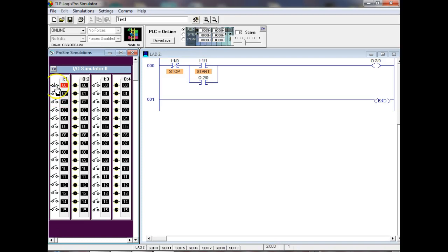Now notice what's happening. This is a normally closed push button, but it says it's true when it's open. But I'm using normally closed, so it's what? False. So I'm coming here all day long and pressing this, and nothing happens. If I change this to a normally open push button, now I come over and press this button, and it says it's true because it says examine if open. So now I'm using a normally open push button as a stop button.